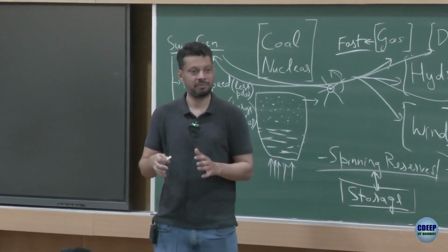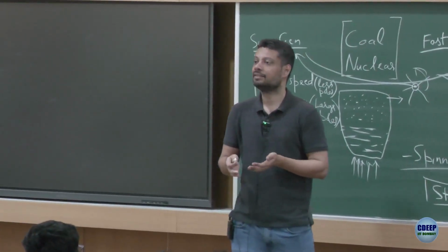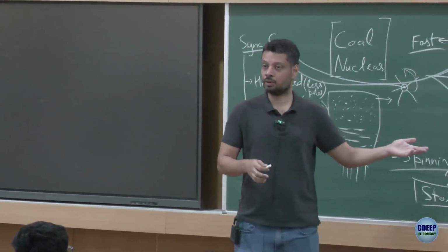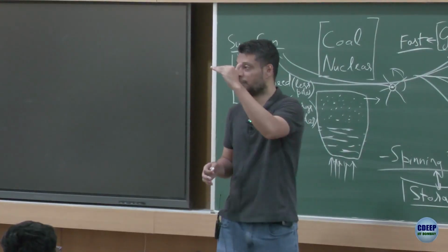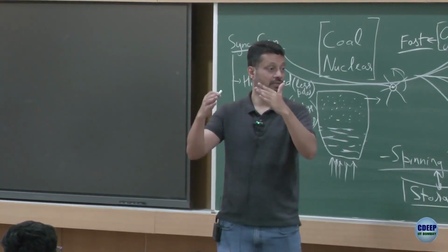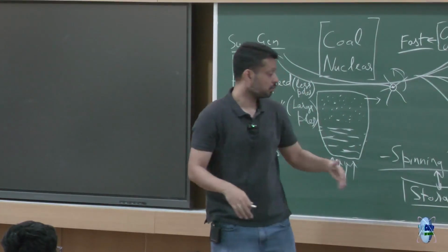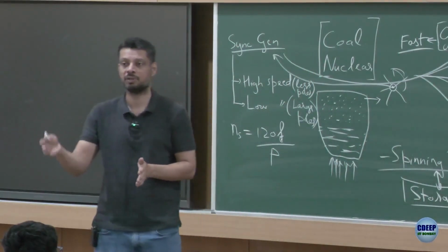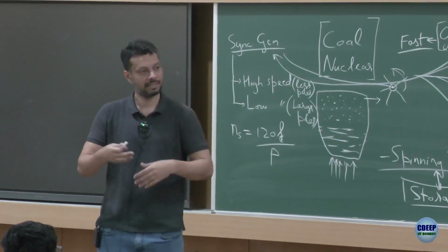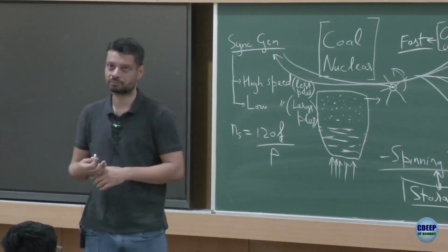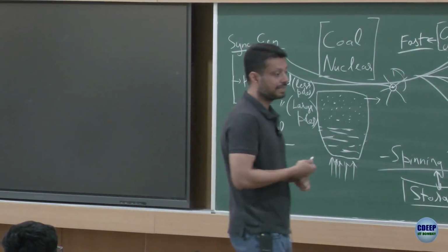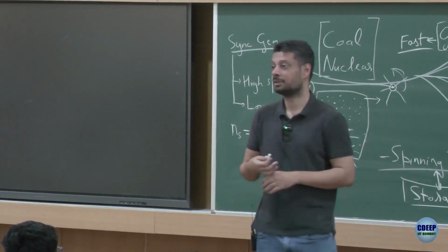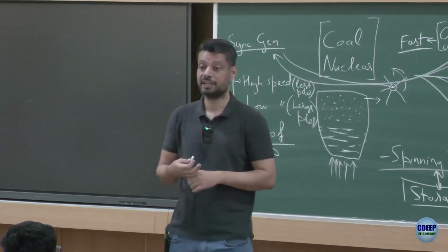But over a period of time, people realized that they can be managed, they can be controlled up to a certain penetration level. If the penetration of these sources becomes even larger, you can go to some sort of storage technology. So as we move towards more and more renewable integration, things are evolving. There's another good example of this variable generation. Denmark has a lot of wind.